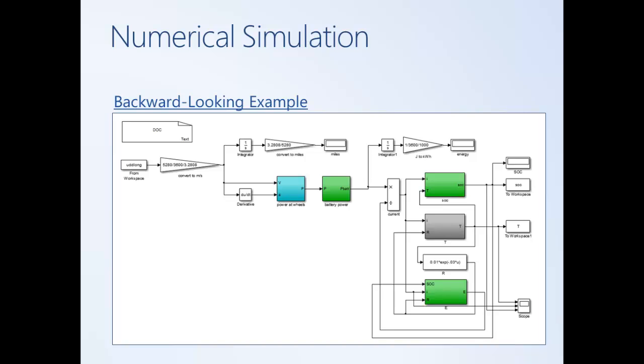So this is a static model. It basically tacks on the different road loads due to grade, due to air drag, and determines how much power is needed to make the vehicle meet the drive schedule exactly. This power is then used to determine how much power needs to be drawn from the battery, and this block consists of just a map based on the efficiencies of the battery.